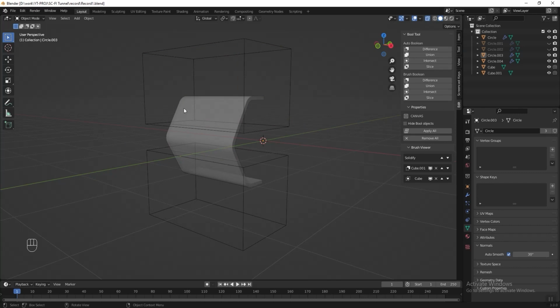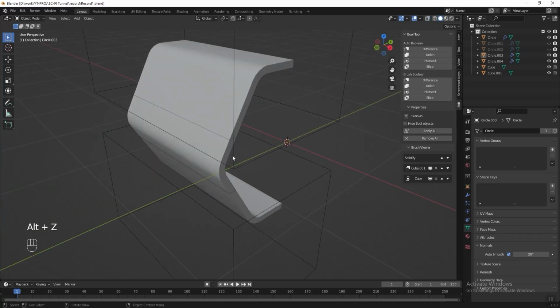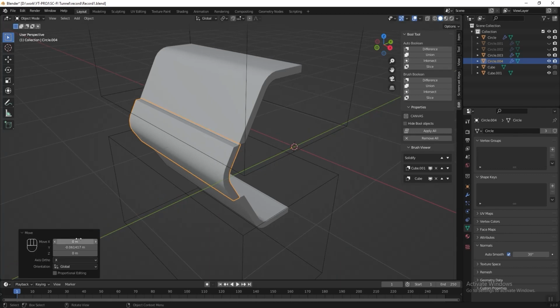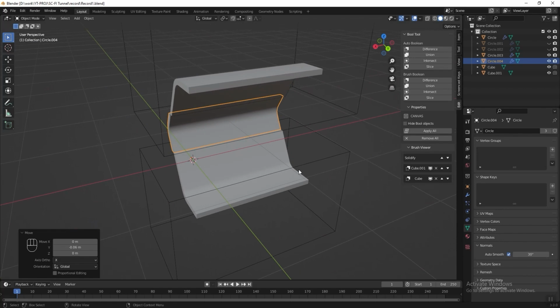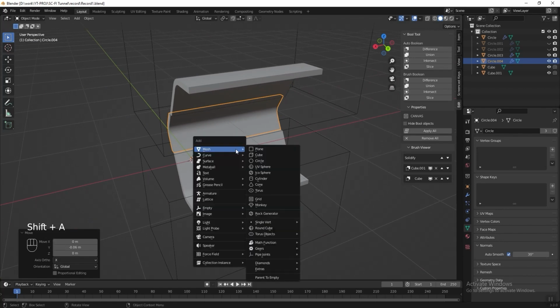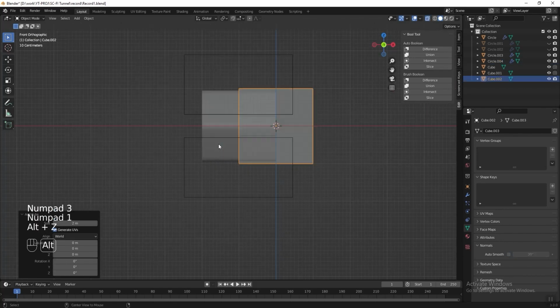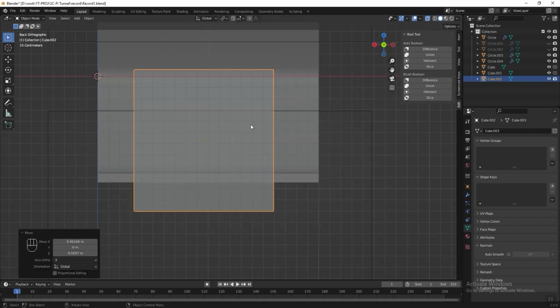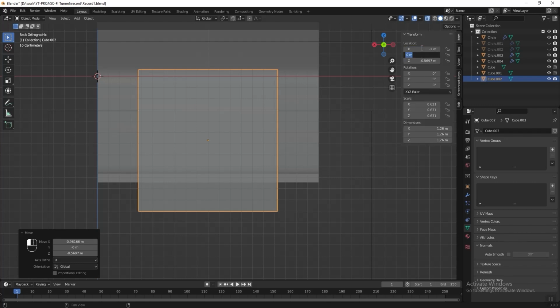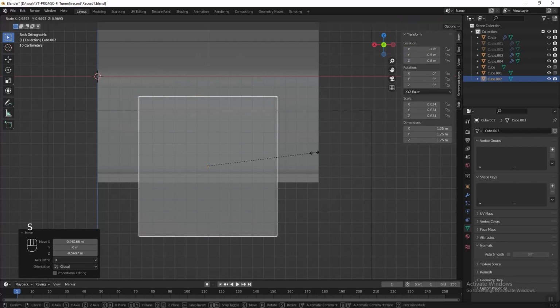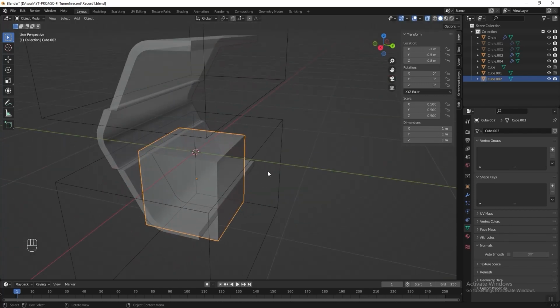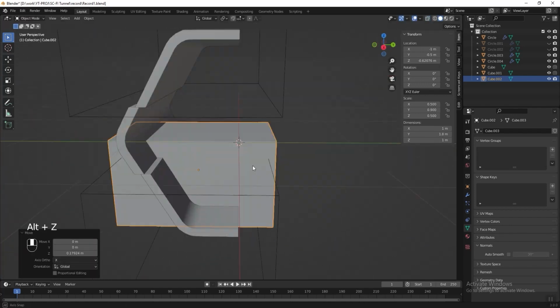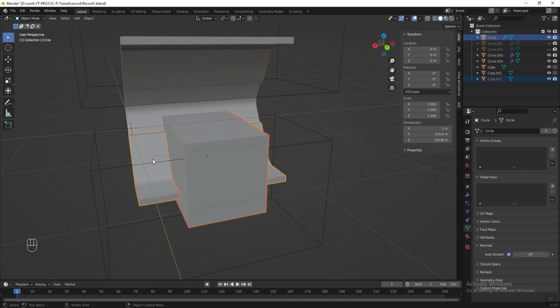And now we can move 3 of these parts separately. So let's move the center part slightly behind. Put -0.06 maybe. Then I think we can add another cut for the bottom part. So let's add another cube. Cover the area we want to cut. Then select the cube and select the mesh we want to cut. Go to Edit and click difference.